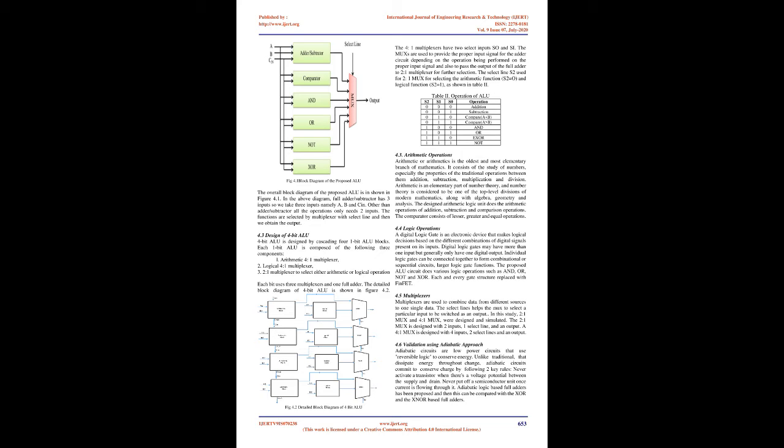Akash Agarwal et al. [10] review the different adiabatic logic families. Different logic gates have been implemented using different logic families and using the proposed DC-DB PFAL logic at different frequencies and for different values of DC voltages for the new logic circuit. Finally, a combinational circuit, a 2:1 MUX, has also been implemented for the proposed and the conventional logic. From the simulation of existing logic families we have seen that the PFAL logic family provides much lower power dissipation as compared to ECRL and 2N2N2P logic families.